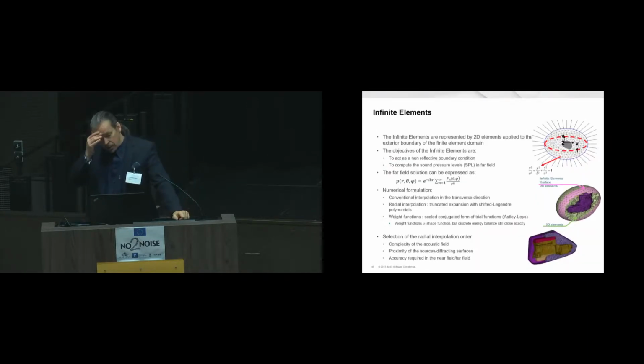Another method that is interesting also is the infinite elements. There the idea is a little bit different. The idea is to bypass the limitation of the finite elements in terms of paving infinite regions by using a different kind of mapping than is traditionally used for finite elements. This mapping will push some edges or faces of the elements towards infinity, so that basically you will define infinite elements that cover a portion of the exterior space but extend towards infinity.